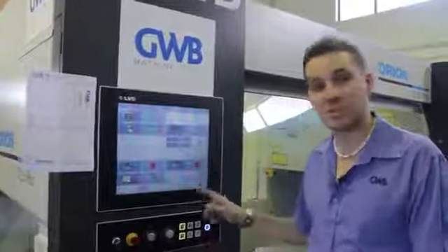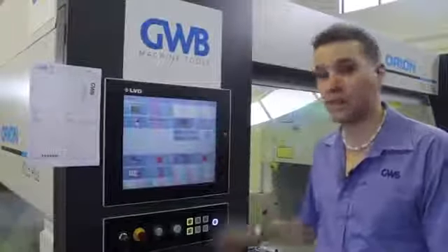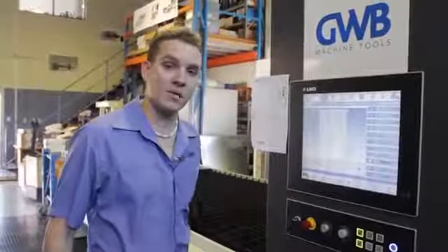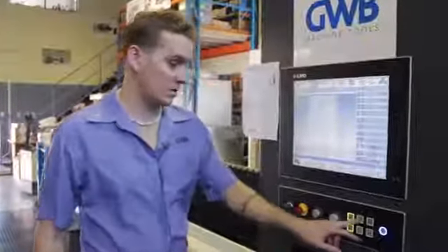We also have a couple of other options here if we want to turn them on and off, such as film burning, pre-piercing, and the location we want to start the job. We've already loaded the machine up with a sheet, so we're pretty much good to go with this one. So we've set our machine up now, we've put the correct lens, the correct nozzle, we've loaded in our job. All we need to do now is press start, and the machine will start the production.